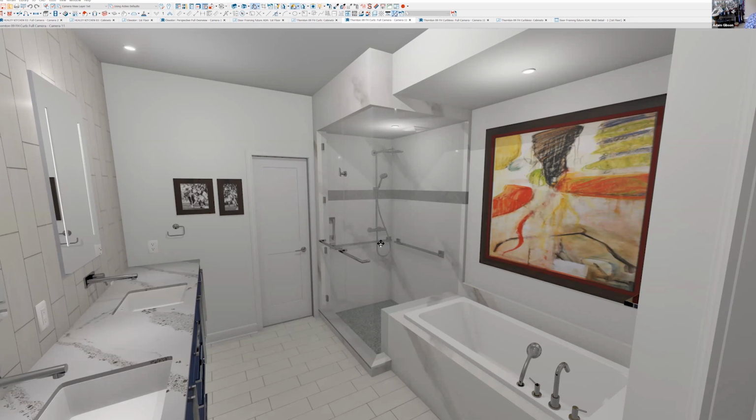They do have to be fastened correctly, and it's not the norm where you just put in some framing. I think that if you're using some sort of hollow wall anchors like Wingits that are designed to hold 250 pounds apiece, that's better than putting them into solid framing, because you never know what you're going to hit behind the drywall or the Durock or whatever. You don't know if you've checked or cracked the wood. And the last thing I want is to get a call from the ER saying, hey, you know that grab bar? Well, not only did it come out of the wall and the tile has to be repaired, but I have a broken bone. So I try to follow all the rules and make sure they're assembled correctly, fastened correctly.